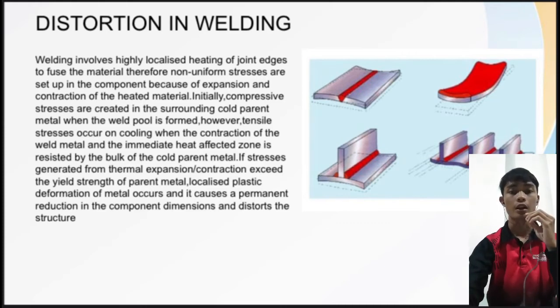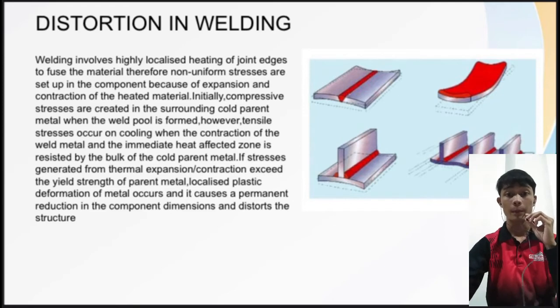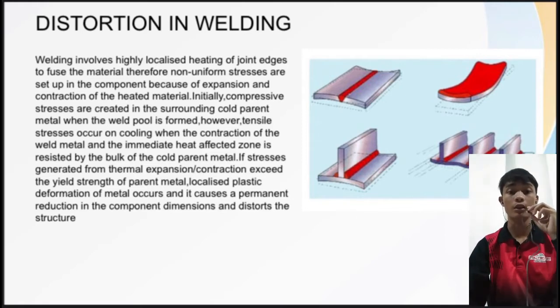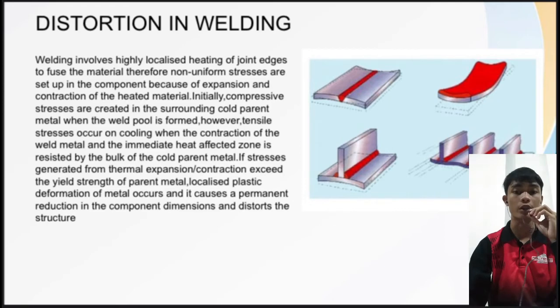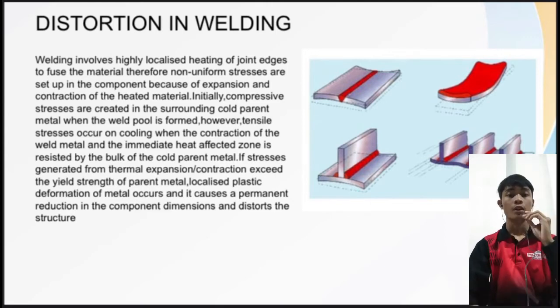Initially, compressive stresses are created in the surrounding parent metal when the weld pool is formed. However, tensile stress occurs on cooling when the contraction of the weld metal and the immediate heat affected zone is resisted by the bulk of the cold parent metal.